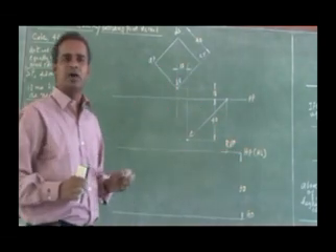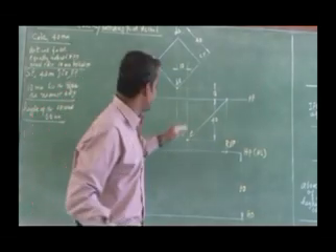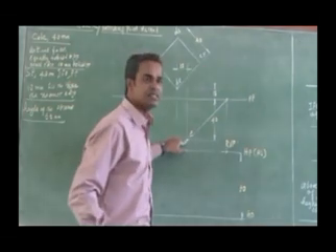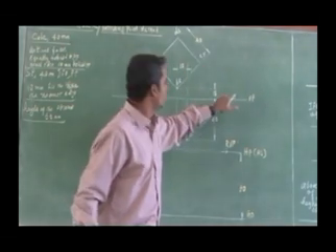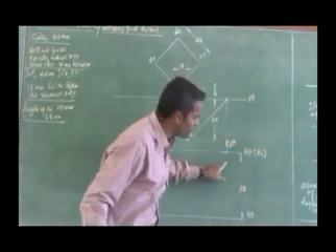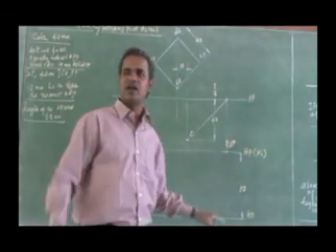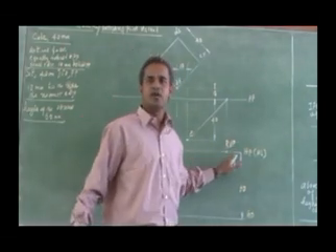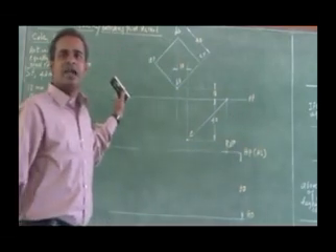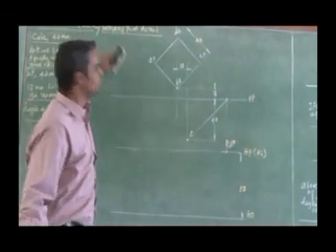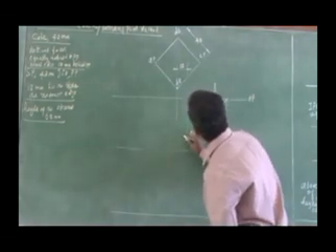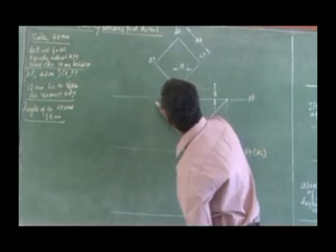So to obtain a vanishing point, first of all you have to draw a parallel line to one inclined face from the station point, get its intersection with the picture plane, then project that to the horizontal plane, since my vanishing point will always fall on the horizontal line. This is my right side, so the right vanishing point. Similarly, I can get a left vanishing point parallel to the face BQAP. Right. So from the station point, I am drawing a parallel line to face BQAP.